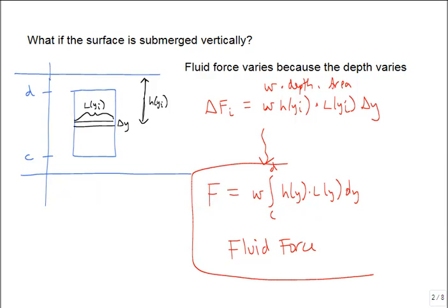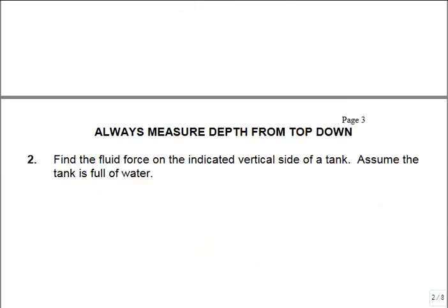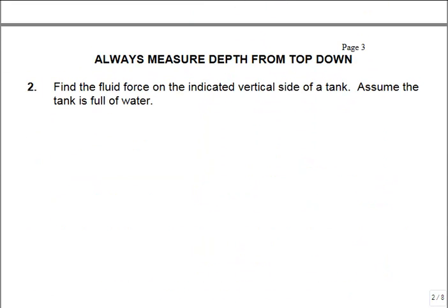Okay, so this is going to be the formula that we're using for all of our problems. The weight density times the integral of the height times the length dy. Now when we're doing these, one word of advice is to always measure the depth from the top down.